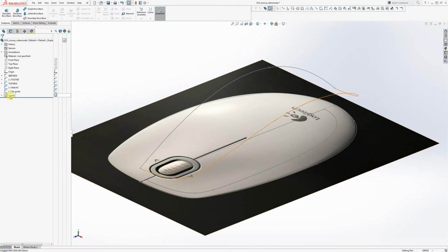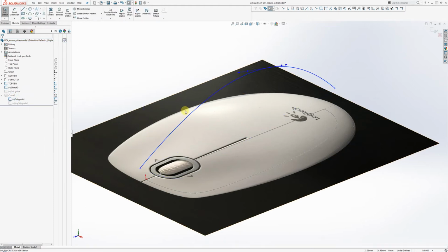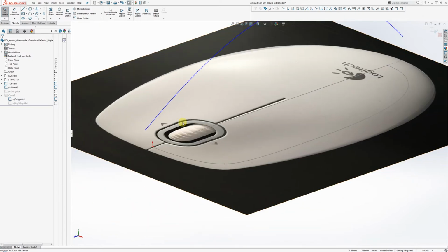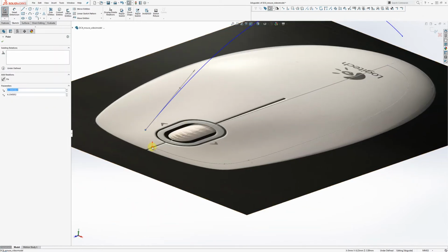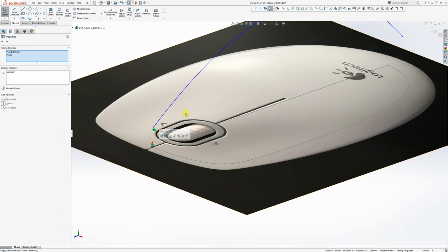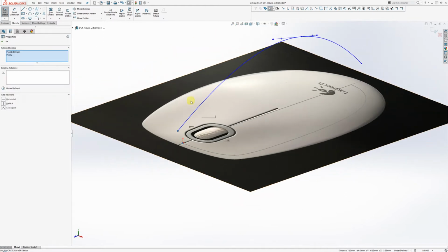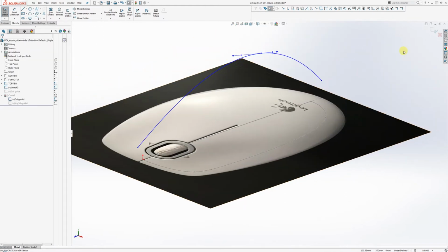Once you finish the 3D curve, it's going to show up in your design tree like this, curve number 2. And you can see that there's a little gray box next to it. You can open that and display the two curves that are driving this 3D curve. So if there's any problems with your 3D curve, you can go here and edit these curves one by one and just double confirm that, in fact, these edges are lined up. Okay? So there we go.